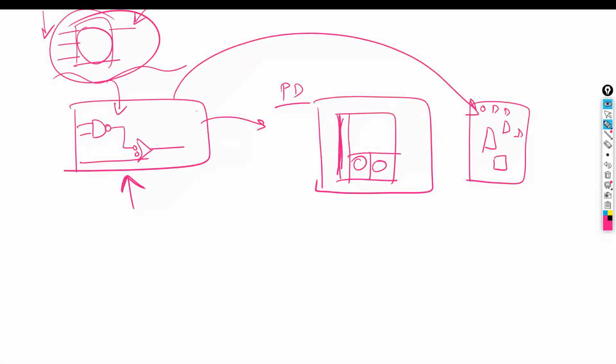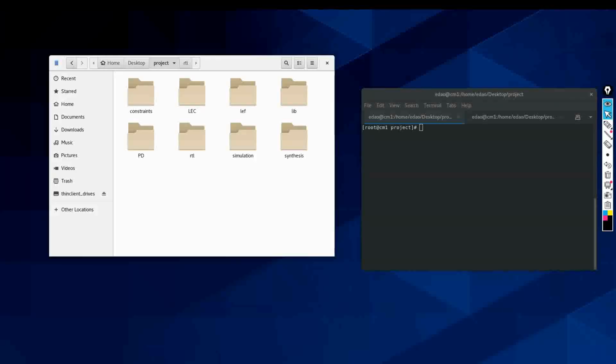To check whether the timing is correct or not, you will do clock tree synthesis. Once this is clear, then you'll do the routing. How will you route? How will you connect your wires? Then you have your different stages of GLS, and then physical verification and sign off. Any questions till now? Any questions you guys have?